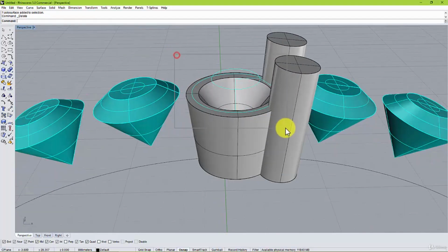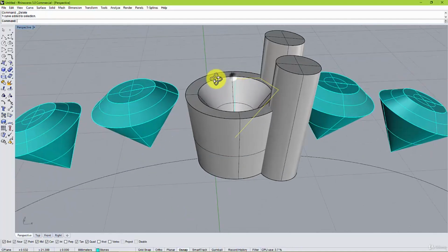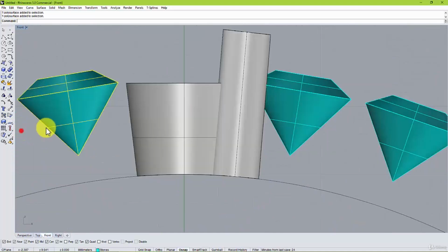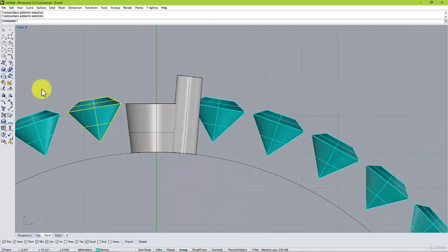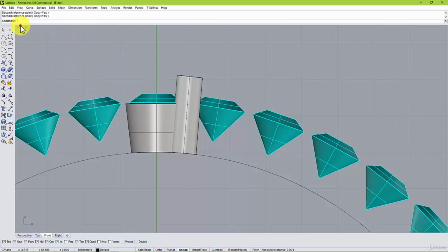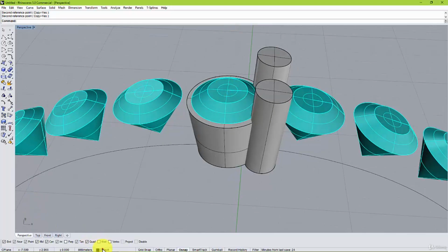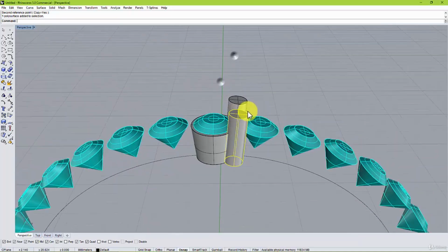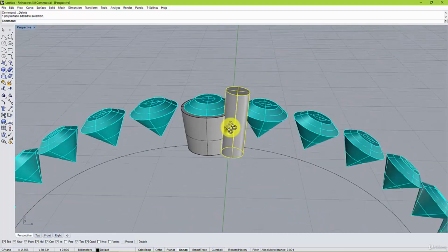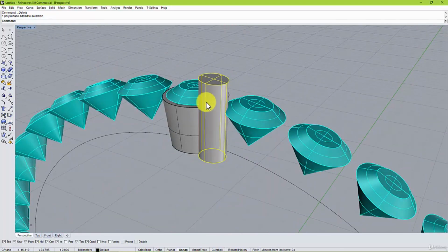Okay, don't worry if you lose the stone, because this to me looks a bit better. What you could do is rotate, you select the stone next to it, rotate, center of rotation 0, enter, and copy yes. So first reference point here, second reference point here, and you got it back. Okay, so you basically sacrifice one stone to make a hole, which fair enough. Also, I think this claw, I'm going to change it a little bit. I might taper it a little bit.